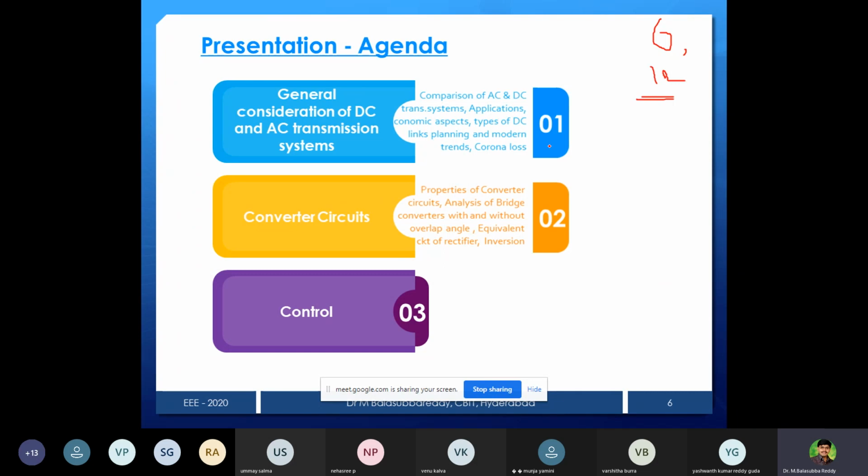Another one is the voltage source converter, which is generally used and consists of a number of devices. There are 6 devices. Preferably IGBT is used for normal applications. For high rating applications and transmission line applications, thyristors only are used. In the case of IGBT, an anti-parallel diode also has to be connected.